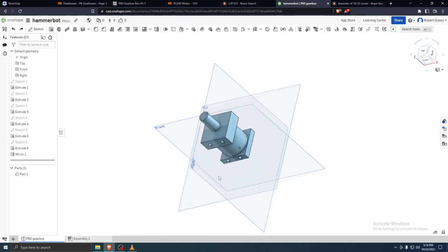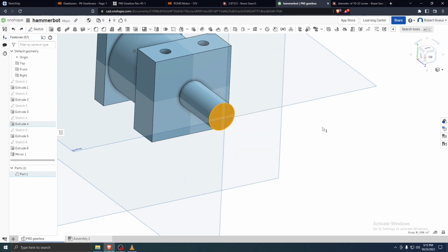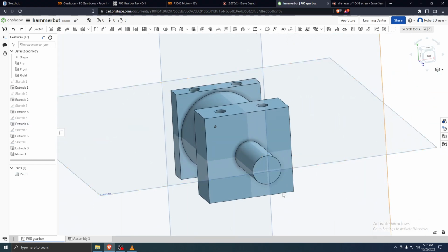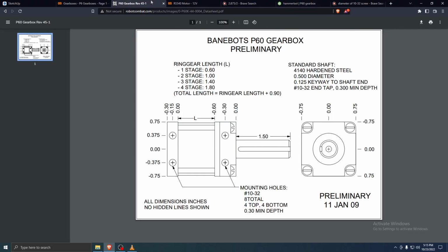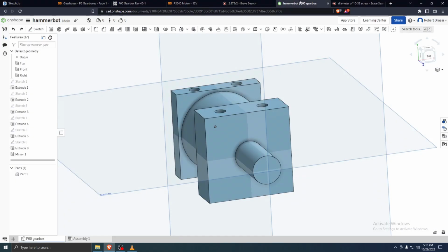This is the gearbox, and there's another feature that we didn't make on the gearbox before because it wasn't really necessary for planning stuff out. But if we want to get nice and fancy here, we can do it. So let's go back to our dimensions. You see, these gearboxes don't have a sharp edge. They actually have a radius. So it's a curve. So what we can do here is simulate this curve. I don't see anywhere where it actually tells us the radius of the curve, so I don't know how steep the curve is, but let's just make something that looks like it's correct.